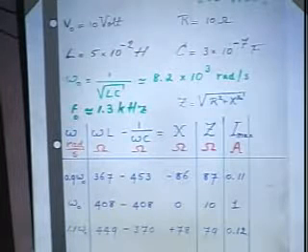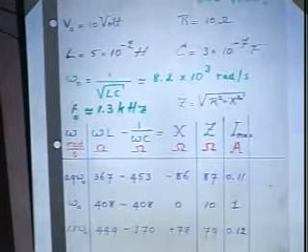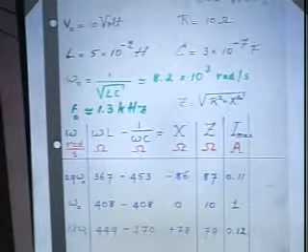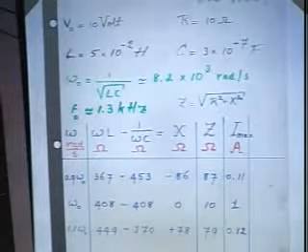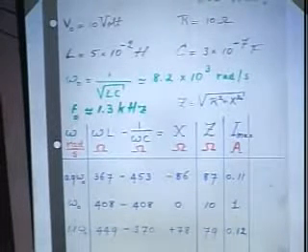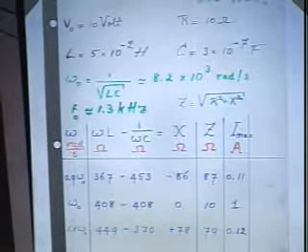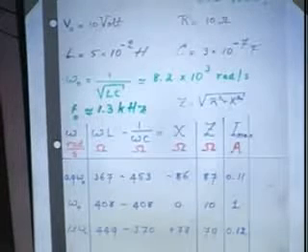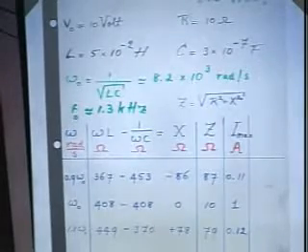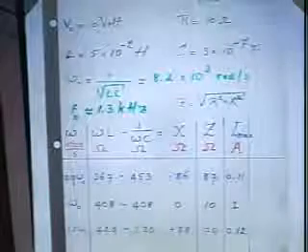We have here, given R, L, and C, 10 ohms, 5 times 10 to the minus 2 Henry and 3 times 10 to the minus 7 farads. The resonance frequency is a little over 8,000 radians per second. You see it here in kilohertz, and you see here the impedance. And what I do here, I have a driving frequency which is 10% below the resonance frequency. And I calculate for you here omega L, which is 367 ohms, and 1 over omega C, which is 453 ohms. You are a little bit below resonance, and so C dominates. And you can see indeed that this ohm value is larger than this one.